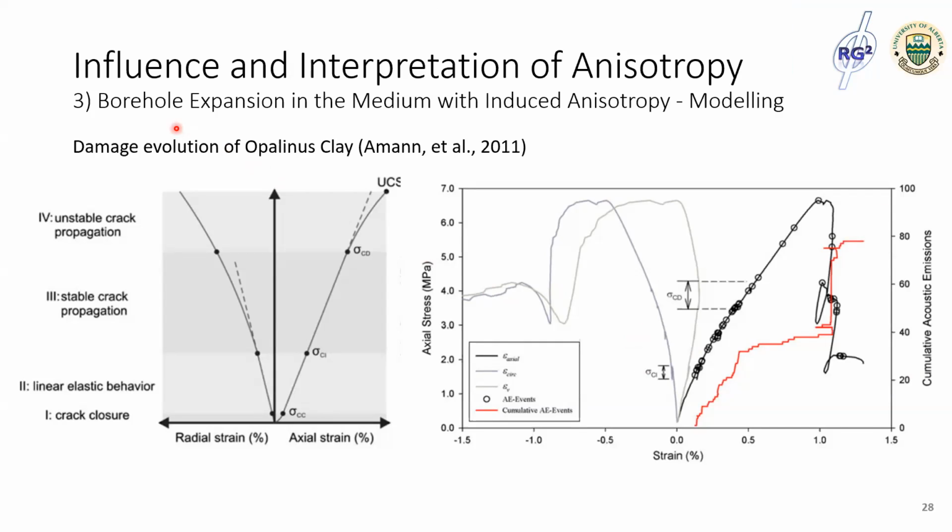That's a hard question to answer. I know this question is from Abel, he's an expert in elastic anisotropy. I think we have to have a good environment or good test conditions to investigate the stiffness tensor, because if you're just doing a pressuremeter test, the loading condition is limited, basically to cylindrical cavity expansion.